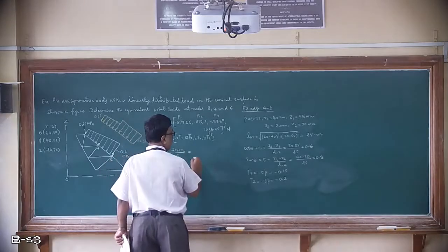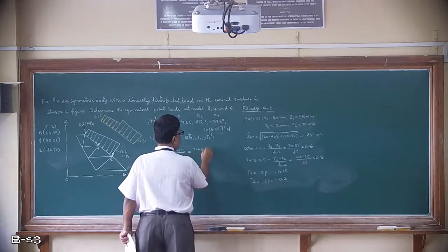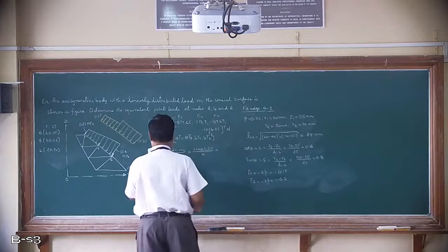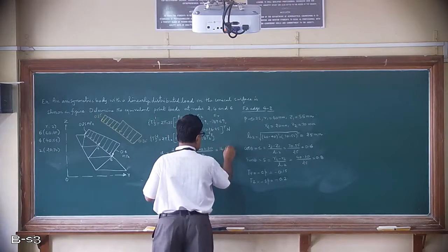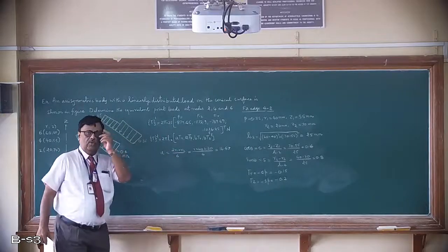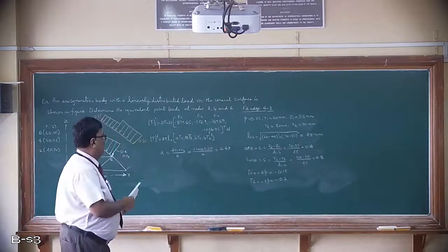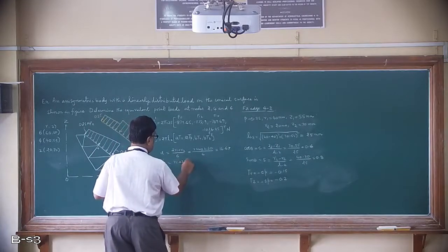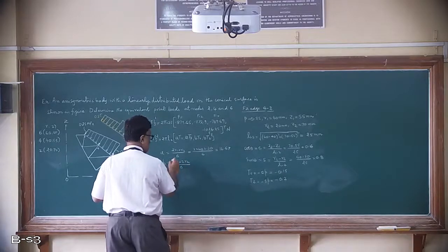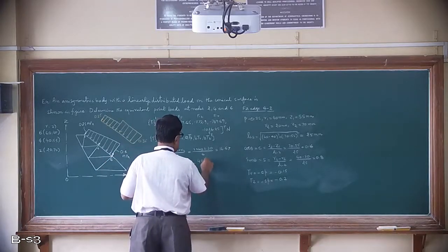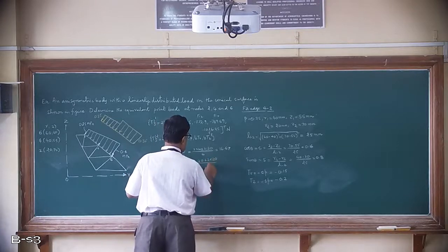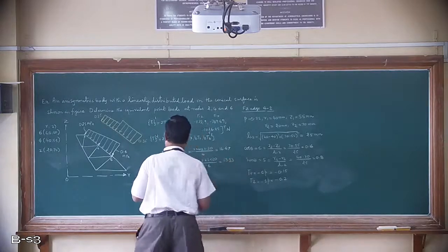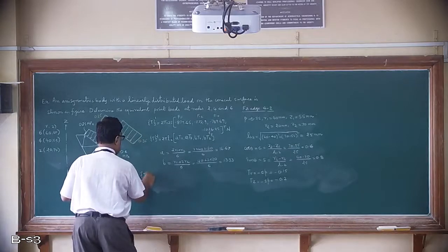That is 2 times 40 plus R2 is 20 upon 6. So A comes out to be 16.67 for the second case. This is what you are going to get. Similarly, you calculate the B part. B, what is B? R1 plus 2R2 upon 6. So this will come 40 plus 2 into 20 upon 6, which is 13.33. So therefore, your next element will come.